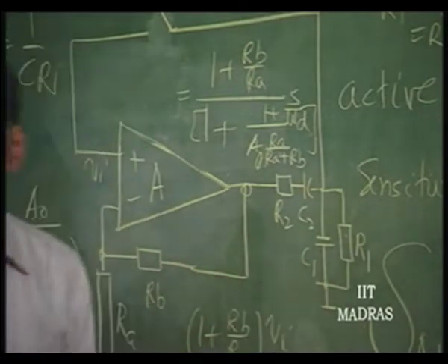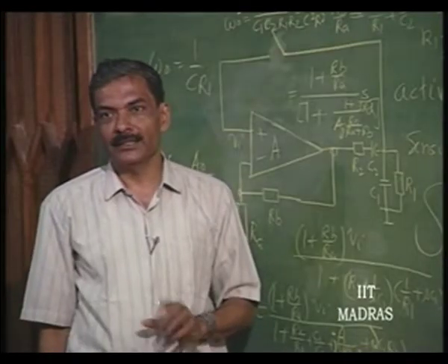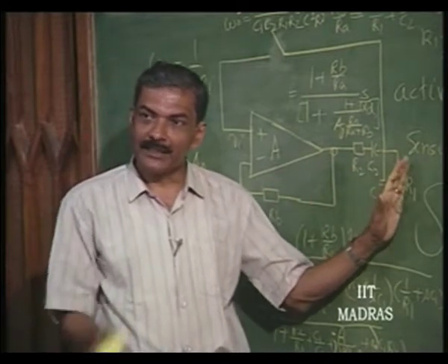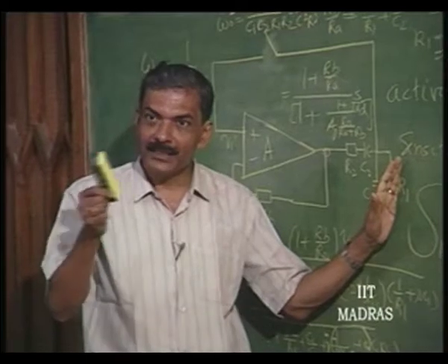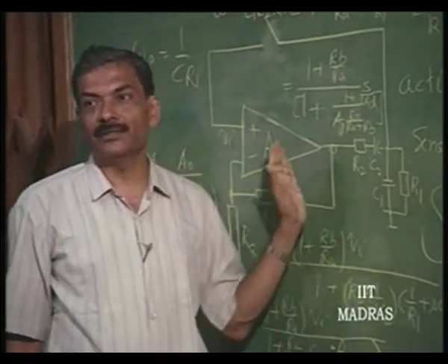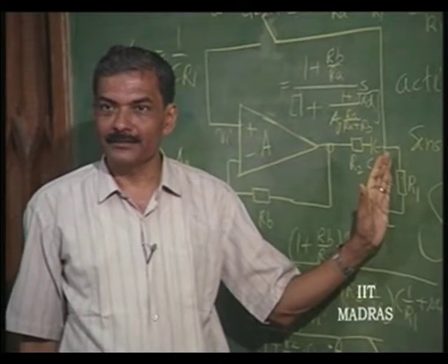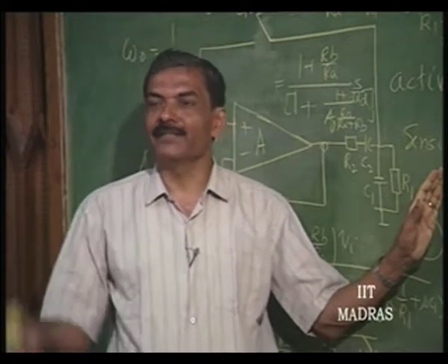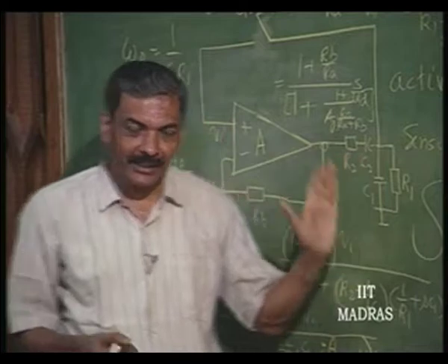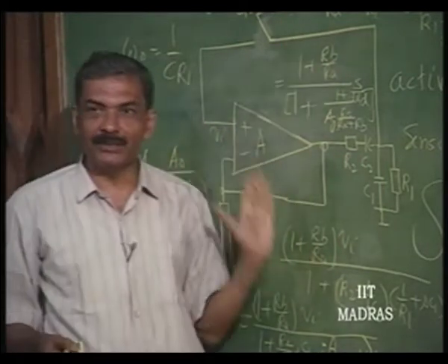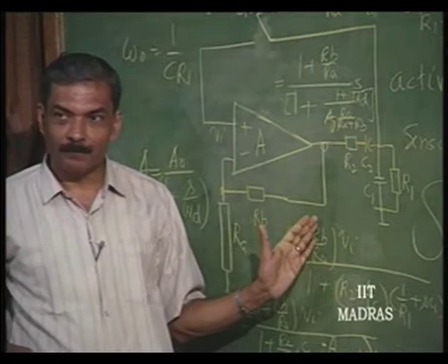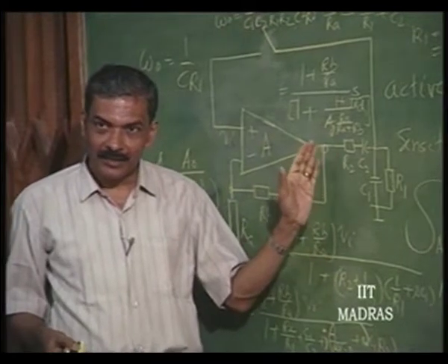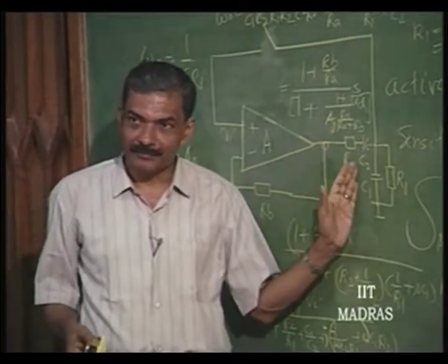Suppose that I compensate at a certain frequency, and for 1 degree it gives you a frequency of oscillation slightly different from omega naught, so as to give a phase lead of 1 degree. Next it changes to 1.5 degrees because of temperature variation, then this will change correspondingly to a phase lead of 1.5 degrees, that means the frequency has to change again. So, now you see how the frequency of oscillation of this Wien bridge oscillator is directly dependent upon the phase variation with respect to frequency here.